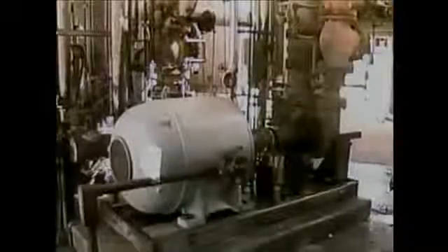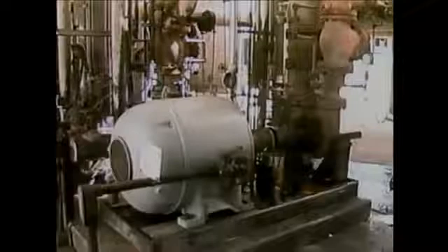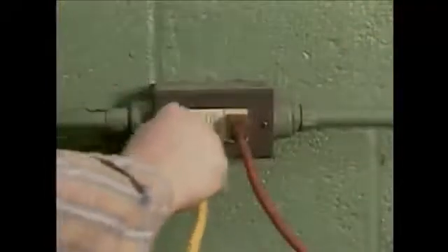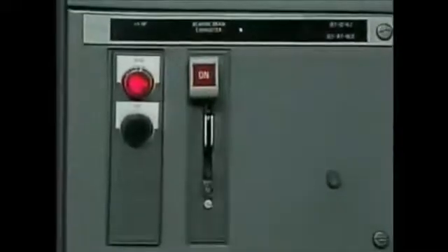The system has to meet the needs of a wide range of equipment, from large motors that operate at several hundred volts to standard electrical outlets that require much less voltage. Distribution systems also contain equipment that has a protective function. Protective equipment helps minimize damage to the system during abnormal conditions, such as short circuits, overloads, and voltage surges caused by lightning. Distribution systems vary widely, depending on a plant's power requirements and its processes.